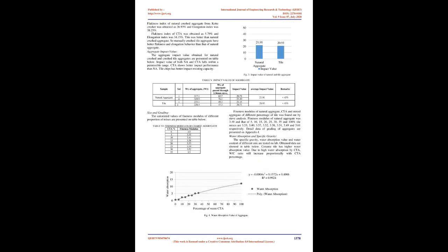Those particles that are predominantly retained on the 4.75 mm, number 4, sieve and pass through a 3-inch screen are called coarse aggregate. The coarser the aggregate, the more economical will be the mix. Larger pieces offer less surface area of the particles than an equivalent volume of small pieces. Use of the largest permissible maximum size of coarse aggregate permits a reduction in cement and water requirements.